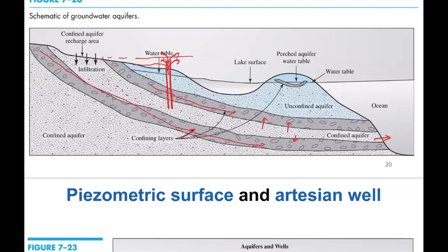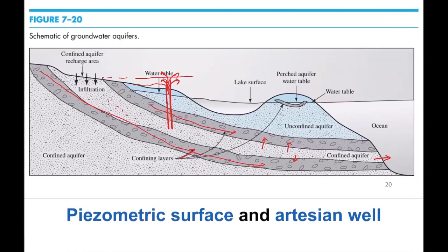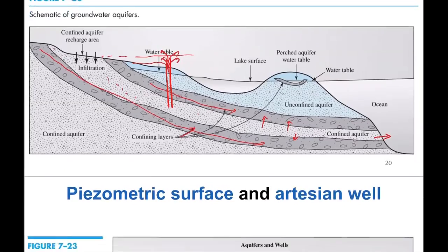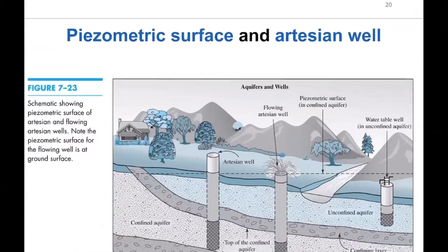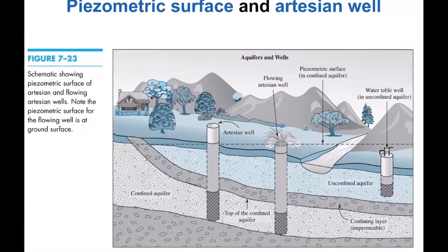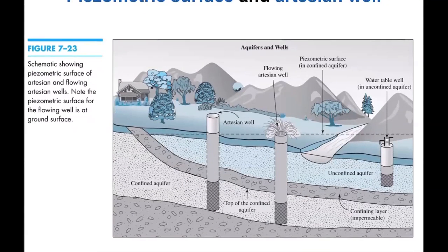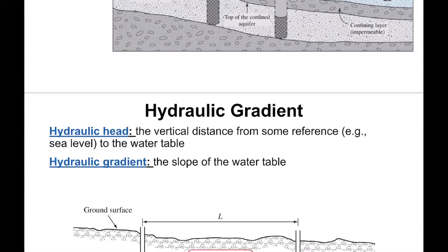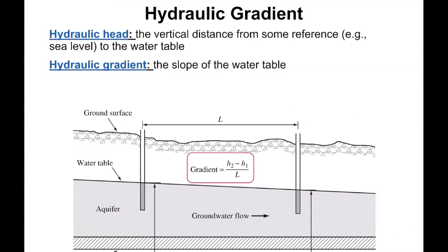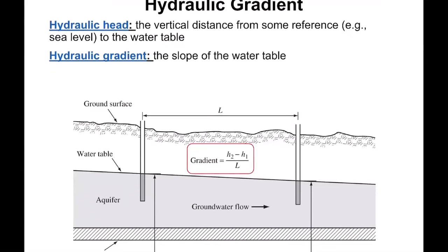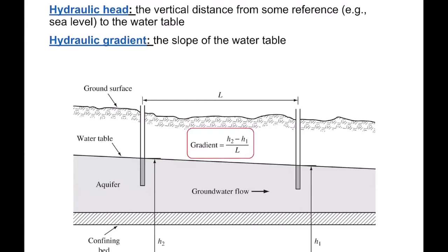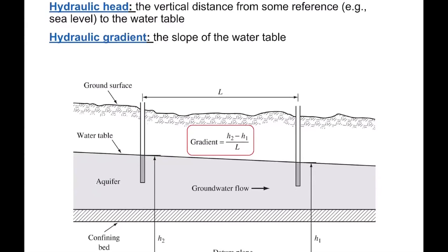So the water here is basically compressed or confined, and you can have this fresh groundwater coming out. So that involves the designs for different types of wells. I have a schematic diagram here. What we want to focus on is the hydraulic gradient, okay? And also the hydraulic conductivity. That describes how fast the groundwater flows in the soil, right?